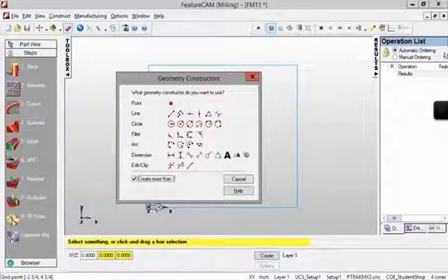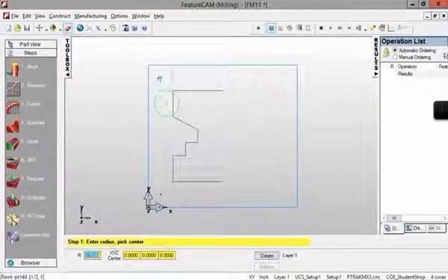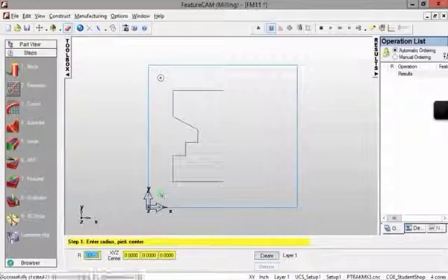So circles are here. There are different modes, as I mentioned. Here you want to use a mode with a center and a radius to define a full circle. The radius here we want to change to 0.125, and then when you move your cursor over the black dots, you can see it is fixed on the center now. And click, you put the circle on already.